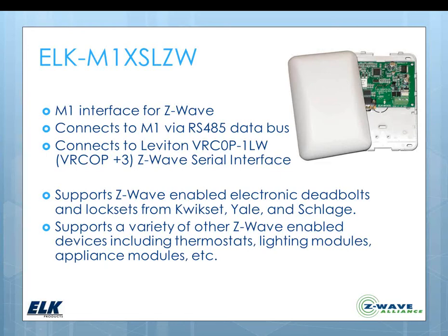So this is going to connect into the keypad bus where you're going to have your keypads and your input expanders, all those devices, and it needs to follow the same rules for wiring as those other devices, as far as no more than 2 runs on the data bus and proper termination, that sort of thing. Nothing new there. If you are familiar with the M1, it's just another data bus device.